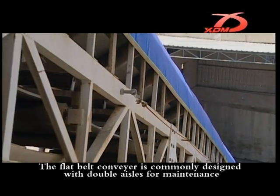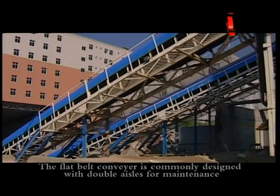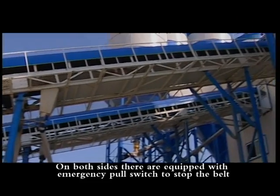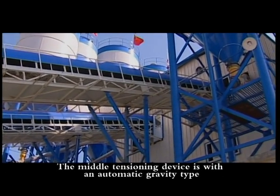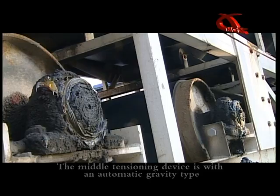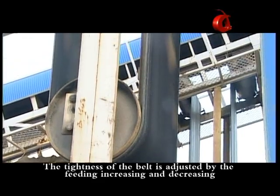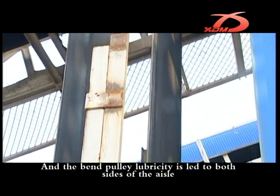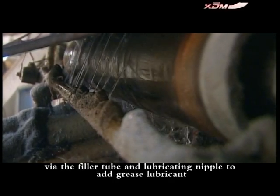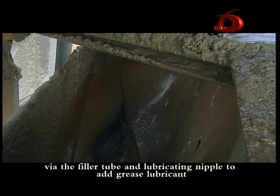The flat belt conveyor is commonly designed with double aisles for maintenance. Both sides are equipped with emergency pull switches to stop the belt. The middle tensioning device functions with an automatic gravity-type sensor. The tightness of the belt is adjusted by the feeding increasing and decreasing, and the band pulley lubricity is led to both sides of the aisle via the filler tube and lubricating nipple to add grease lubricant.